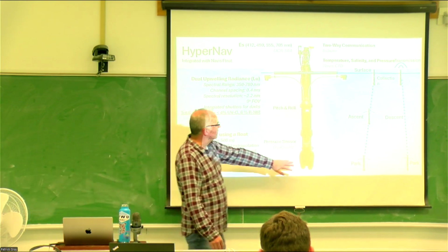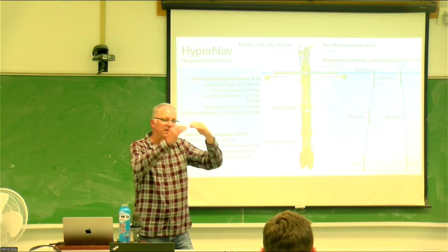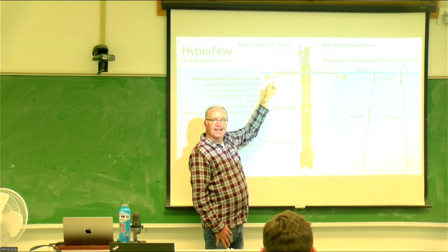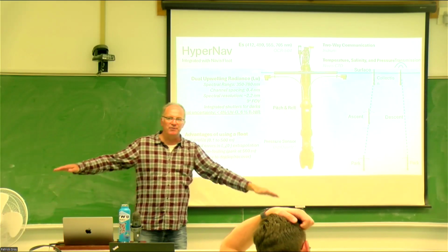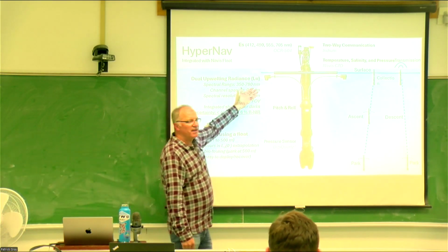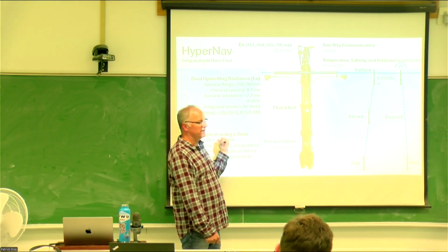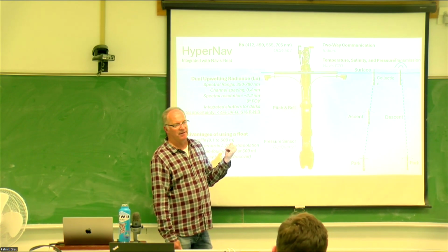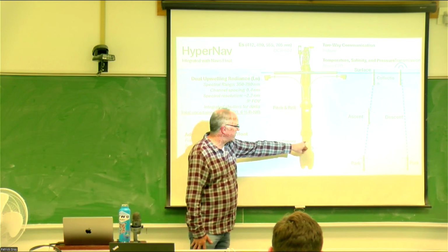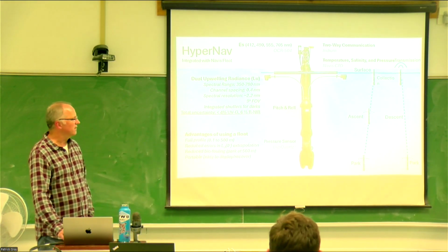So there's batteries on board, but even with the CTD, it's not high resolution enough. The problem is we're trying to propagate over this 10 centimeters, but there are waves, so in the mean it's 10 centimeters, but the heads are dipping underneath. They're not real deep, it's like a quarter meter, they're just bobbing. So over that tiny distance, you have to have really good accuracy in your depth measurement. Otherwise your Ks are going to be blown out of the water, literally. So we have a very high resolution pressure sensor on this system as well, to get the accuracy we need for pretty accurate Ks.